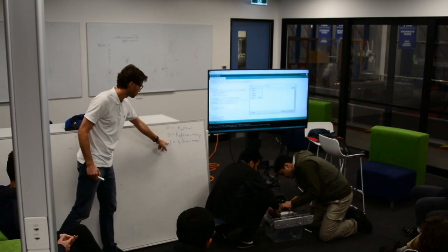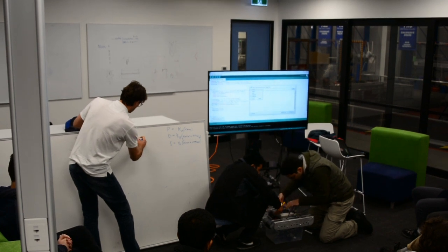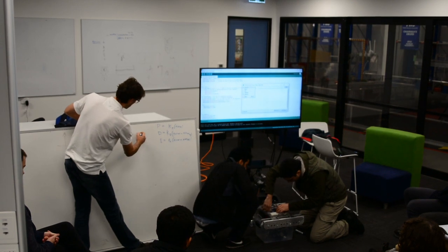So what's the integral controller going to be good for? Anybody remember, or have any thoughts? Let's say we went back to the situation where we had a KP that was kind of low, and we had a large amount of steady state error, just sat there at 990 or 970. Your throttle is going to be equal to the sum of these, right?